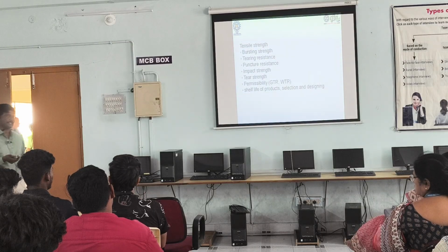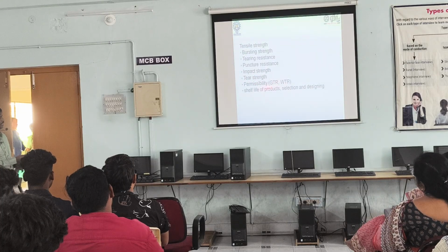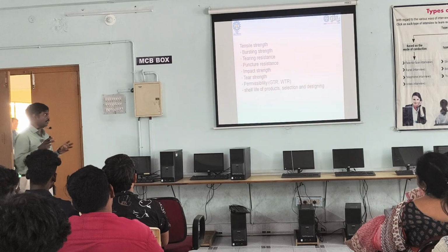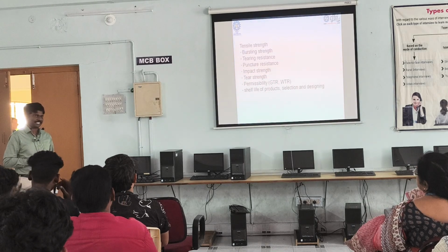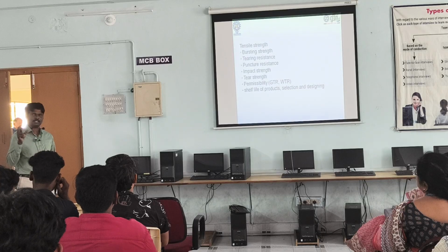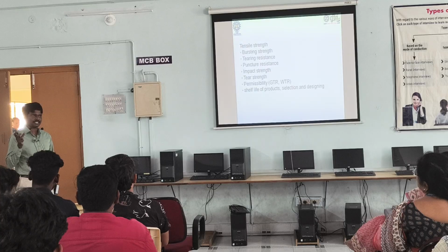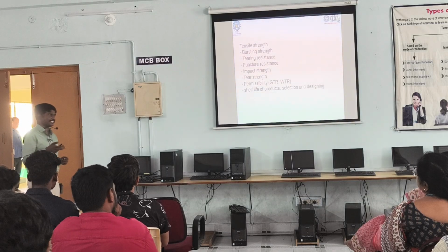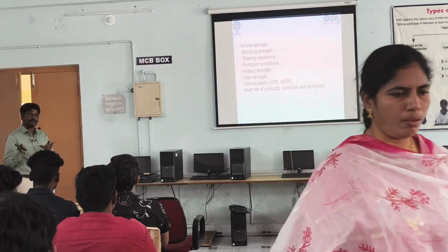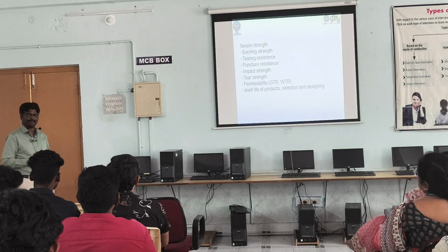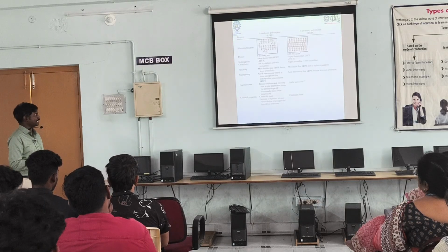How do they design the packaging material? They will take the strength of the packaging material, and water and oxygen should not go inside the packaging material. For example, we have oil packets. So oil packets are more prone to oxidative degradation. So if oil is reacting with the oxygen, then it will form rancidity. There is a chance of it being carcinogenic. That's why the oil packet should not let oxygen molecules permeate inside the packaging material. So that barrier we will need for this packaging material.